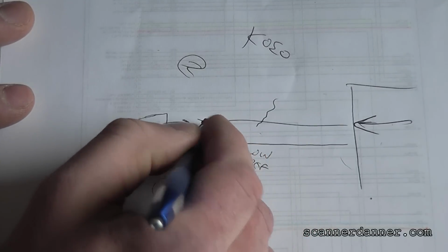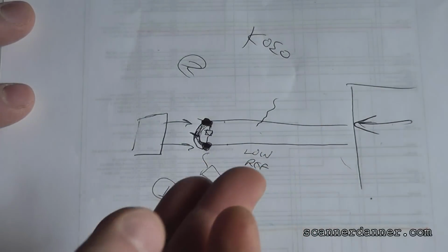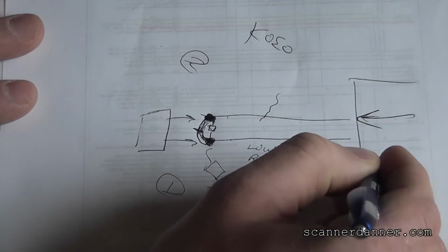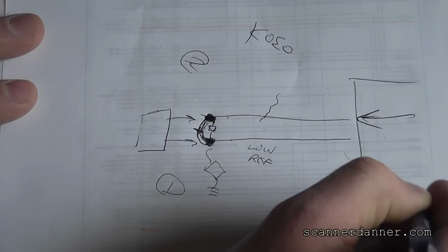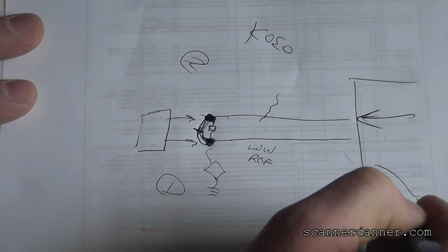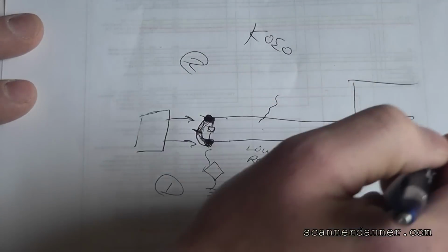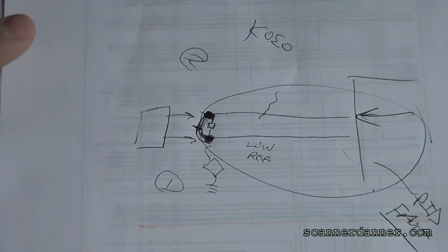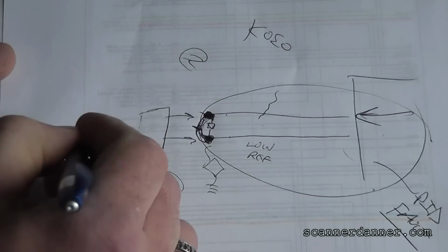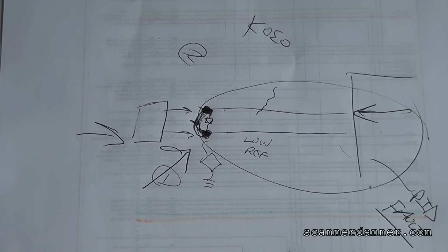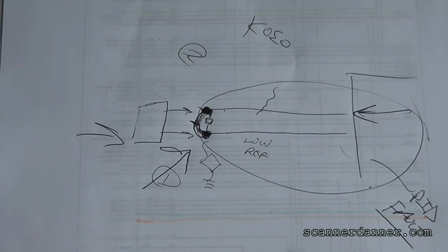We're intentionally shorting the circuit to ground, power side switch circuit. Kind of crazy that they'd have you do that in a flowchart and then look at a scan data PID to say fault. And if it does, what that tells you is the entire circuitry is good, and then we change the solenoid. That is a crazy test. I'm not going to do it this way. Just wanted to show you the manufacturer flowchart.